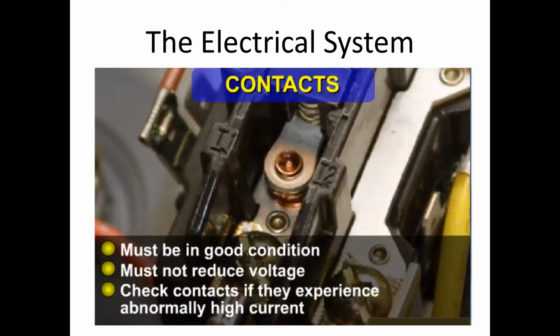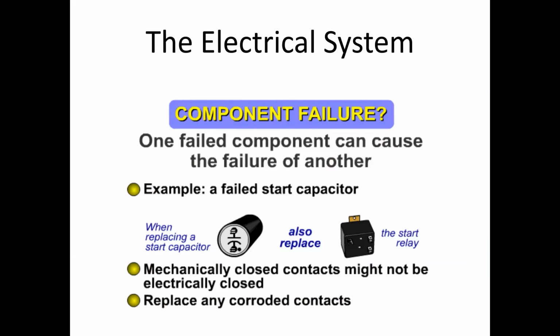We're going to talk about contacts and pitted contacts and how to check for that next week. If you're replacing a start capacitor, replace your start relay. If you're replacing a PSC motor, replace the capacitor for that motor. If you're replacing a compressor, replace the capacitor for that compressor. Don't replace a motor that requires a capacitor to run or start and then not replace that capacitor as well.